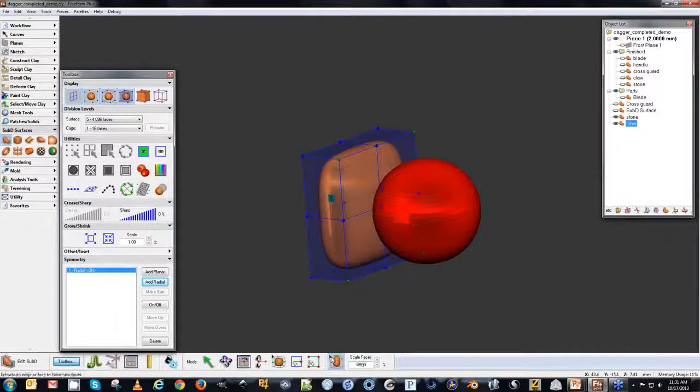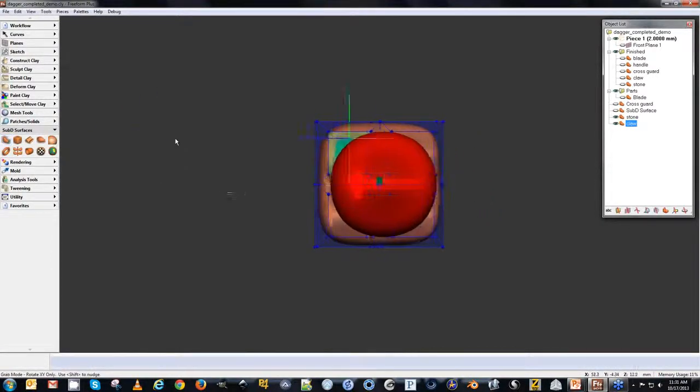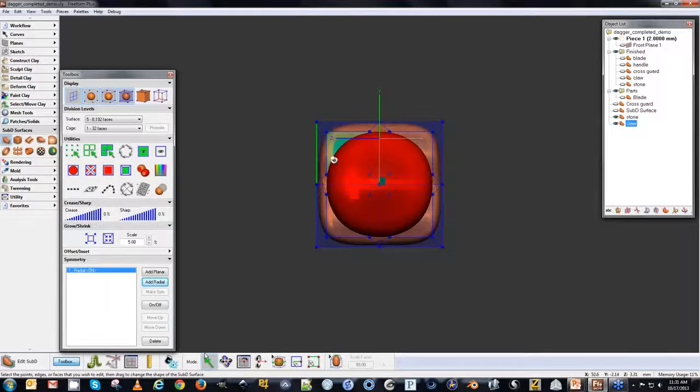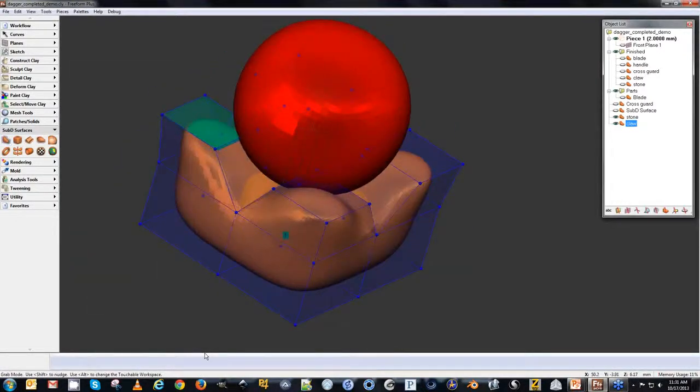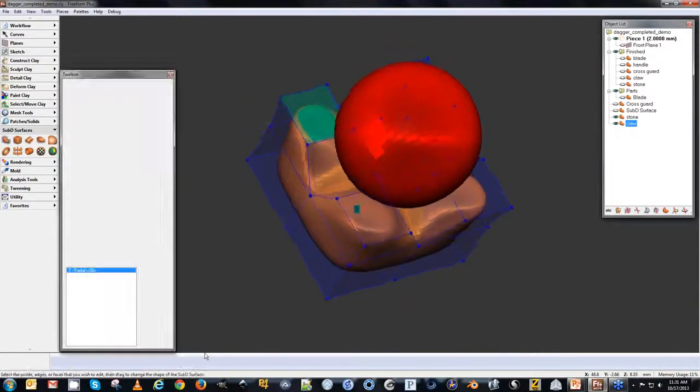If I knock this down slightly and make sure that I'm not fusing adjacent faces, when I click on this and pull it out slightly, you can see that now there are 4 individual faces that pop out, which I can then shrink down in size, bump this up a little bit, and if I rotate around to the back, we don't want them directly underneath, so I will just take those and start sliding these outward. And if you look, that's pretty well sitting on there.